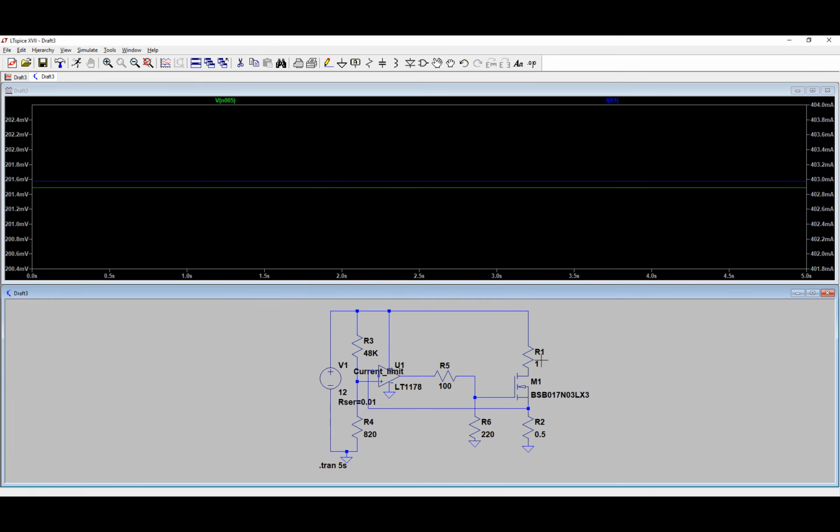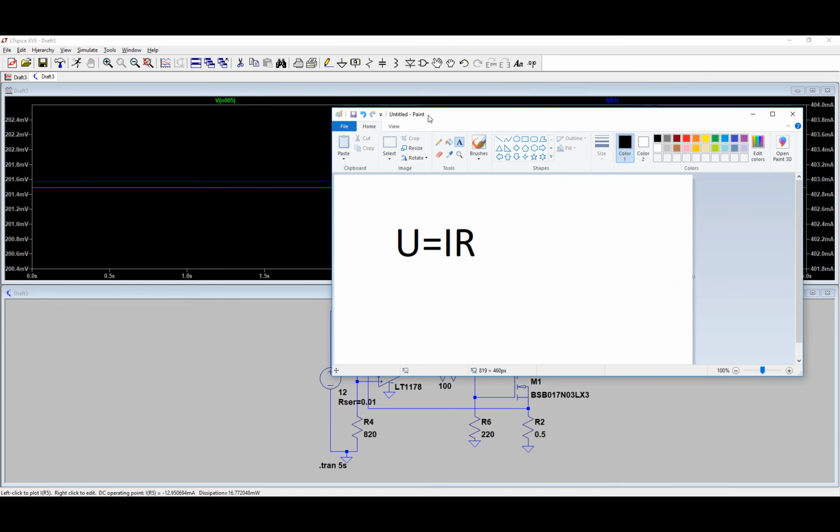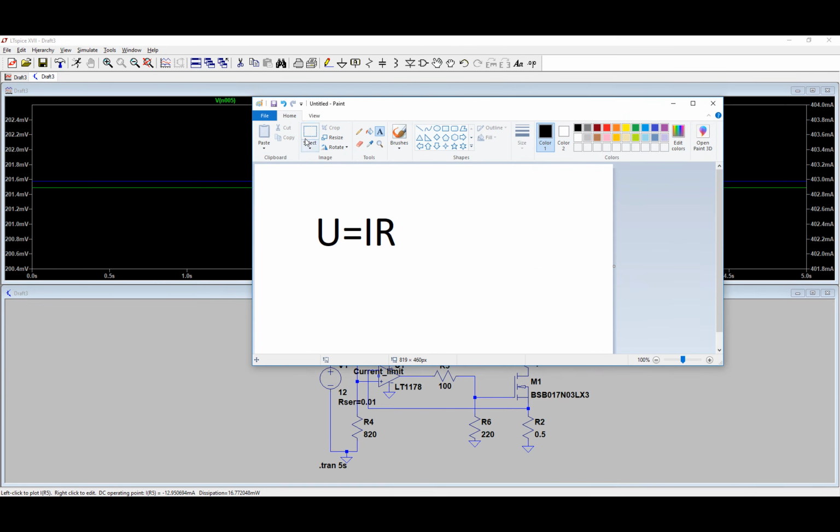Instead of taking this part, this is a linear and I have the parts inside linear, I will use parts that I'm familiar with, and I will give you the numbers so you will know what the parts are. So basically for the Mosfet you can use any N Mosfet with a voltage that is 15 volts and above and has a current of, let's say, 1 amp.